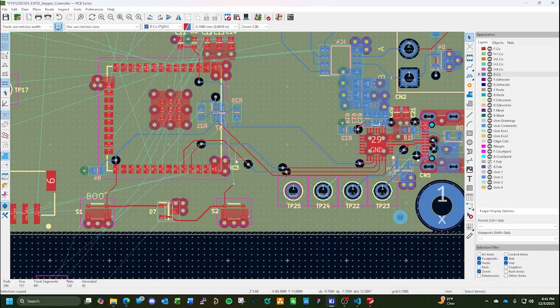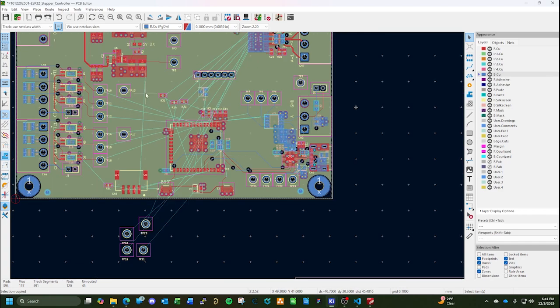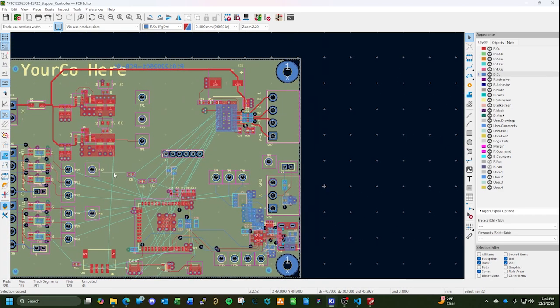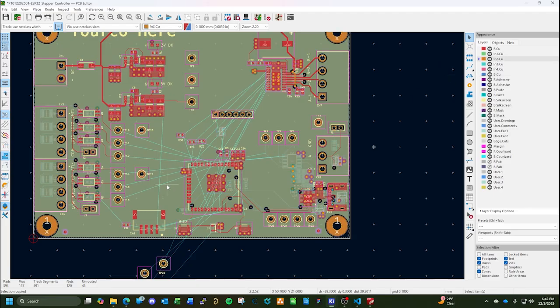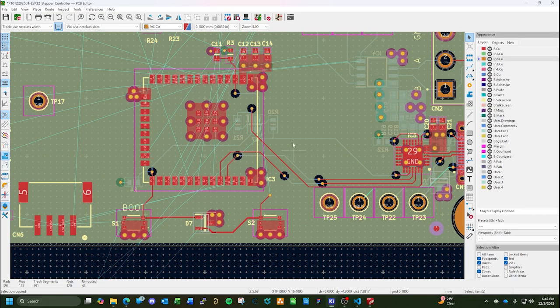You know what? That's a push button. That's going to be a tangled mess of crying and sadness. What we're going to do is bring that through our north-south routing layer, which is going to be the internal signal layer number 2. And we're just going to tie it to the via. Because again, that's a button for manual control.